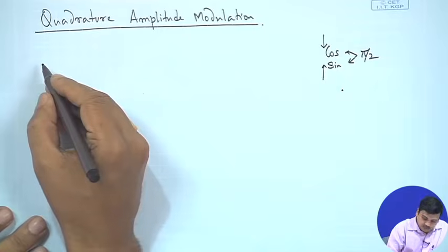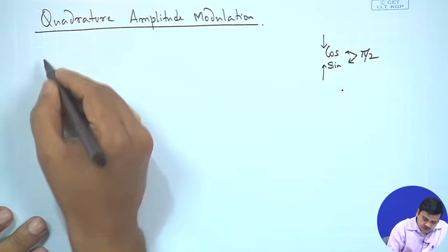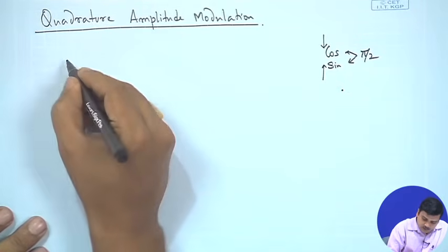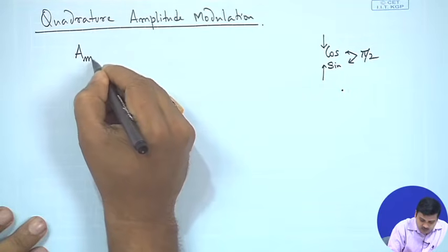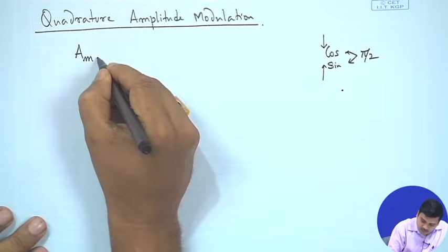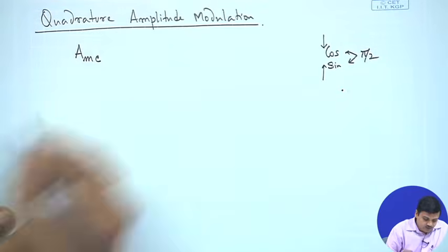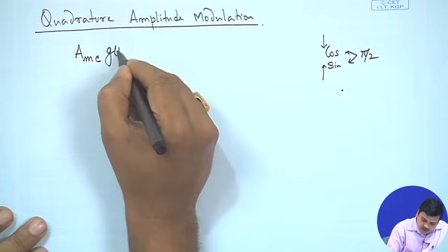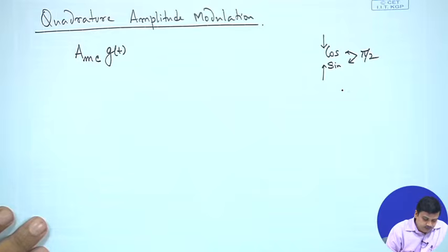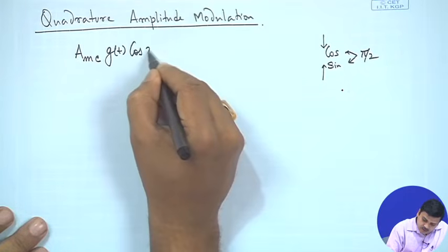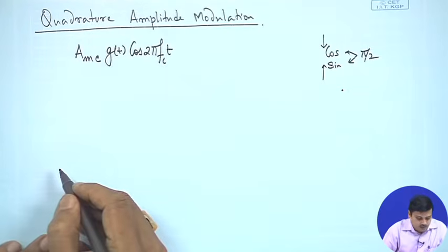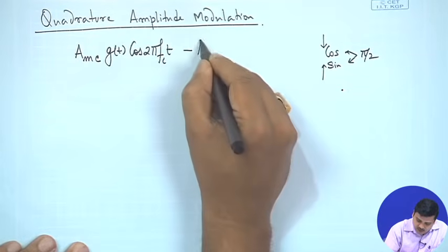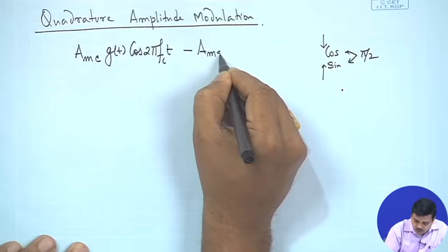So, we could write the signal representation in various forms, and one of the forms, where we change the order of writing, would be the amplitude modulation of the cosine or the in-phase component times the pulse shape and the carrier, as well as the amplitude of the sine component.